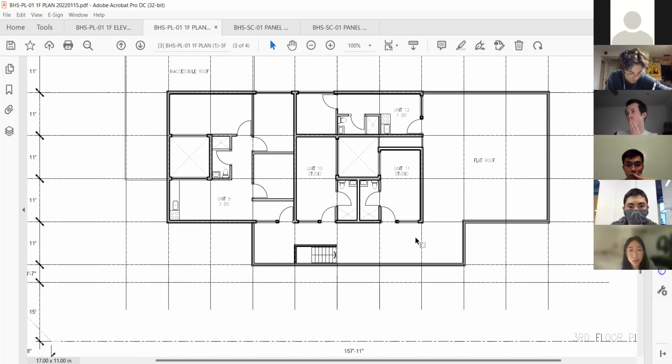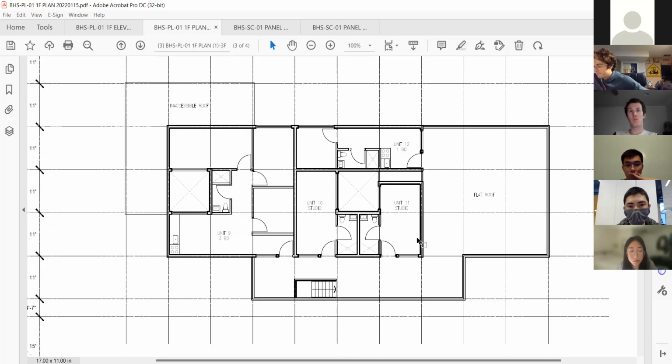And then I'm more concerned about the lateral system. I don't know how in depth we need to get with the structural design. But I think for the podium deck, we would end up with 1.5 or 1.25 inch lightweight concrete, just for weatherproof and waterproof purposes. Of course, in terms of choosing material for waterproofing, there are tons of options to choose from. So yeah, it's your call for that.